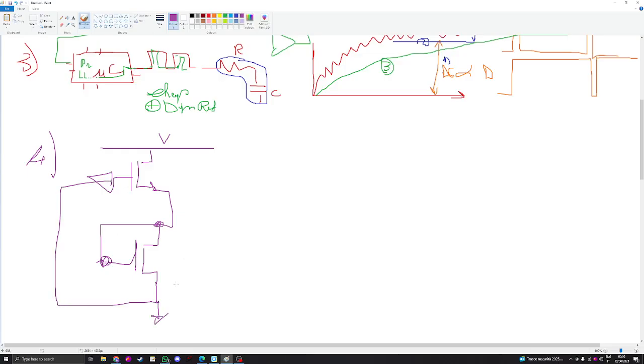The result is that you are exploiting the VTH of your MOSFET, which is quite stable, but not stable enough to be used as a real voltage reference. Yes, you can use that, but you have to be more and more precise and compensate for things.